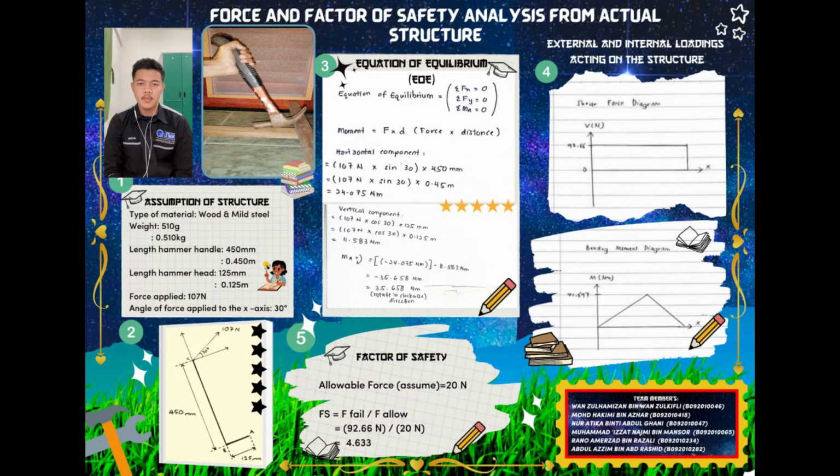After that, the shear and moment functions. Specify separate coordinates x starting from the left side of the beam. Section the beam at each distance x. Draw the FBD of each one of the segments. Determine V and M for each segment using the FBD. Next, the shear and moment diagram. Plot the shear diagram V versus x and the moment diagram M versus x. It is better to draw these diagrams under the FBD that you have created.